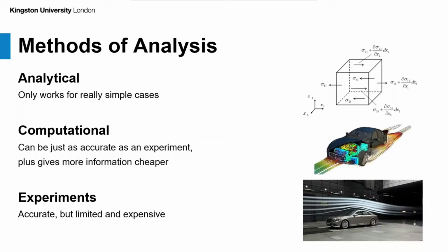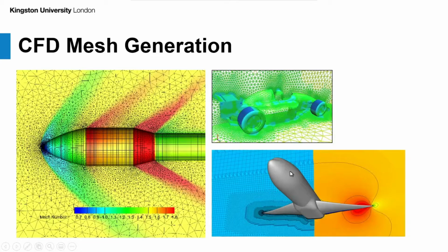So what I have to do is convert my model, or discretize it, into smaller cubes, thousands or millions of them, which we call cells, as part of the mesh generation. Mesh generation is quite important because with those you are able to apply this single equation to every one of these cubes or boxes that we make. The mesh quality will impact the accuracy of the result.